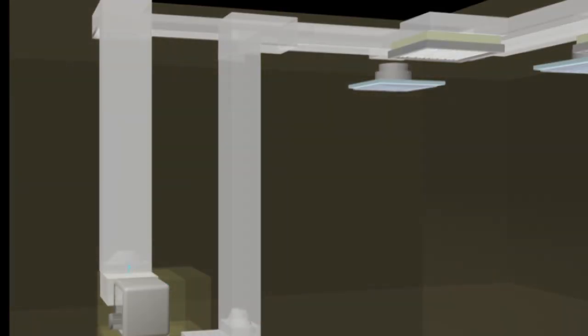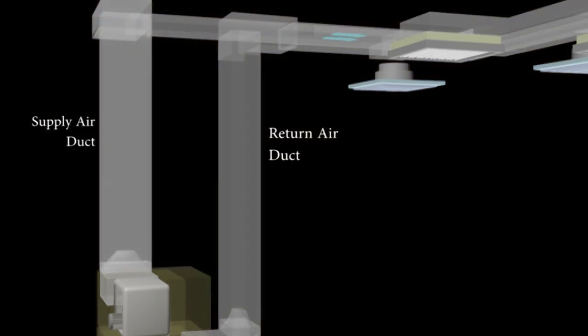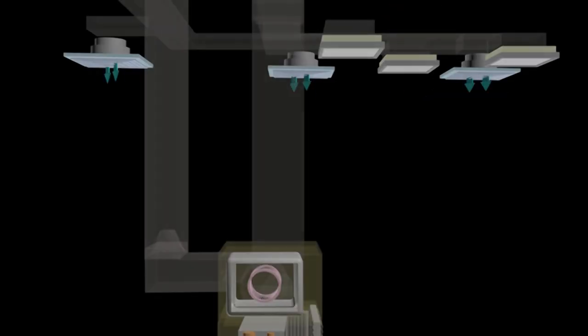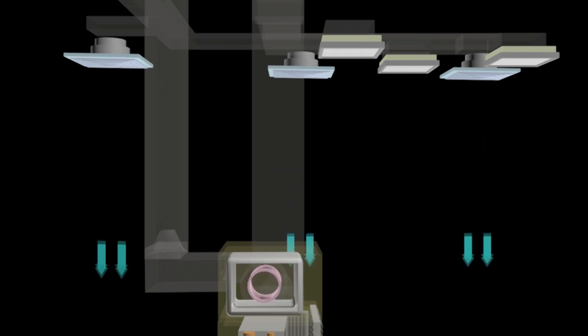There are two types of air duct which are supply air duct and return air duct. These air ducts are coated with insulating material consisting of fiberglass wrapping with aluminium foil. It reduces heat transfer from the environment to the air duct. Air returning to the air handling unit will pass through the filter before passing through a cooling coil and returning back to the room. This is to ensure that the air returning into the room is in a clean condition.